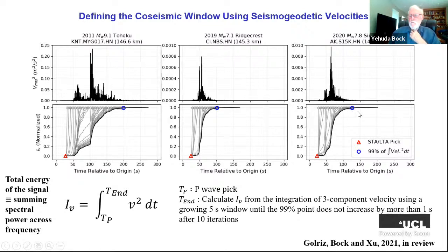And that will vary, could be from a minute to several minutes for a large earthquake. So what we're looking for is the transition from this co-seismic phase, where you have this permanent displacement, and the later post-seismic. Now, knowing the difference between the two is important in creating these fault models, and it has implications for the rheology of the crust. So it's important to know the transition from the co-seismic deformation to the post-seismic.